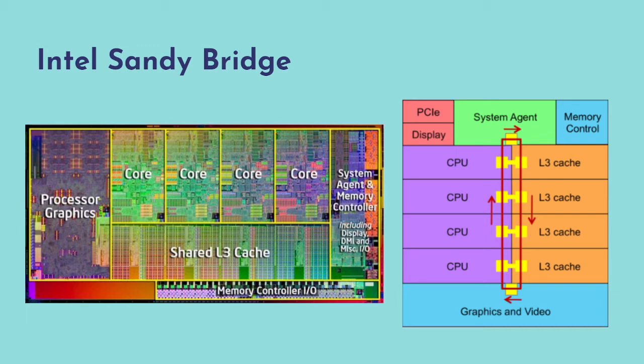The graphics and video units at the bottom of the chip take about 20% of total area, and this unit appears to consist mainly of synthesized logic, whereas the CPUs and cache use custom circuits designed to maximize performance. Also, we have a big level 3 cache that covers 20% of the chip.